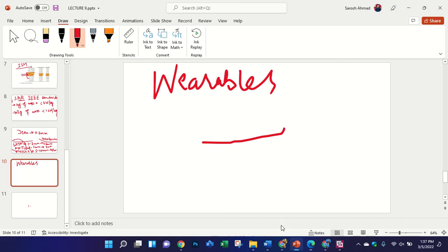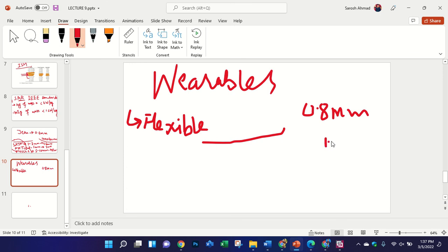So we need two novelty factors. What we can do is make the antenna flexible. In my research paper my design was not flexible. So I suggest you use Rogers 5880 with 0.8 millimeter thickness, or you can also use 1.52 millimeter, because with this thickness you can simulate or calculate the bending analysis in simulation. But in practice you cannot, though it is still acceptable.